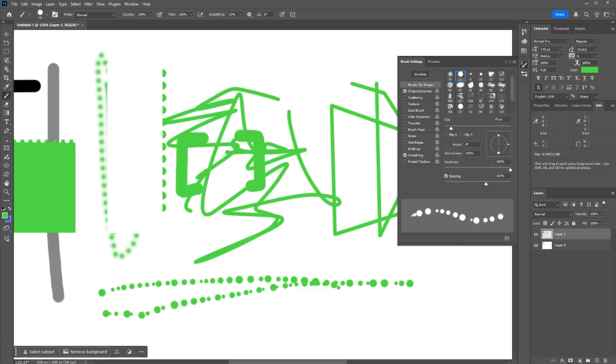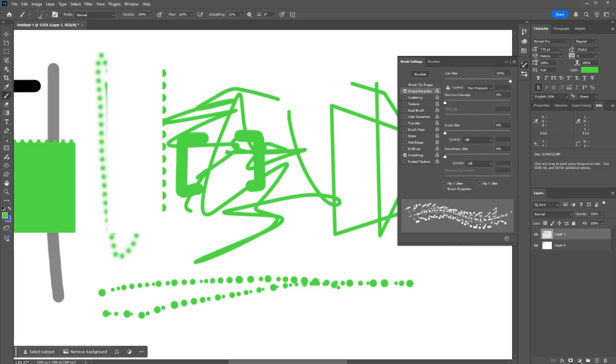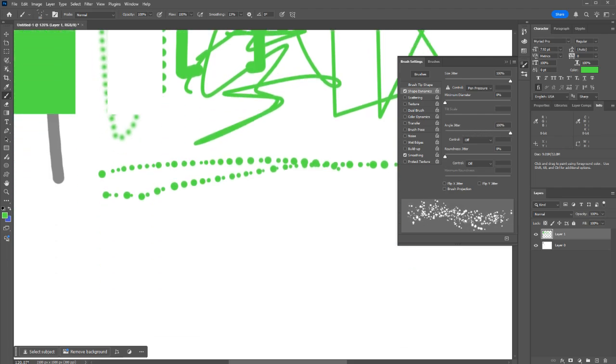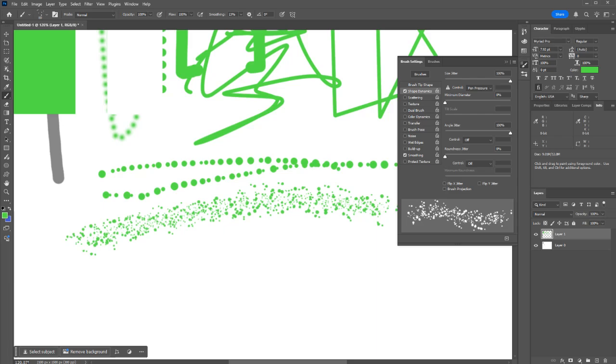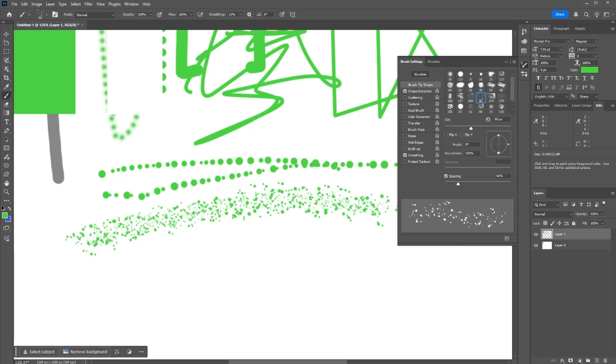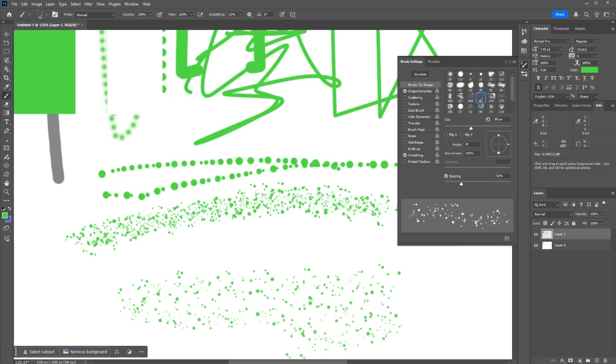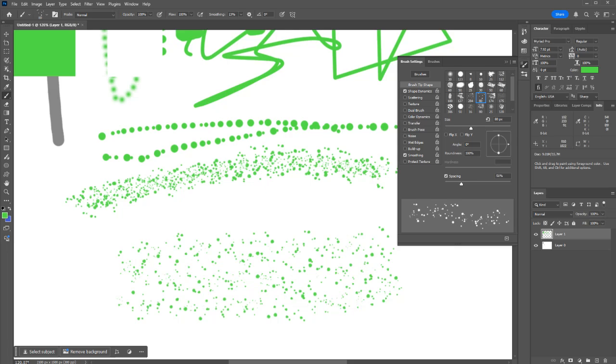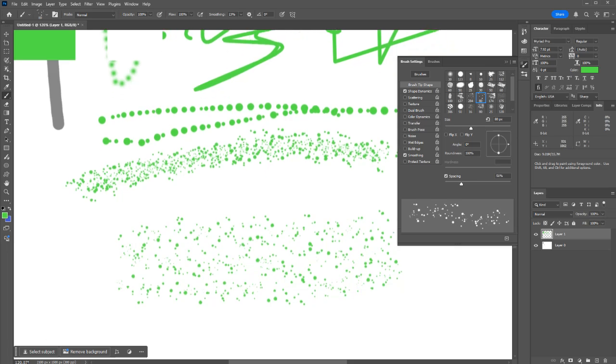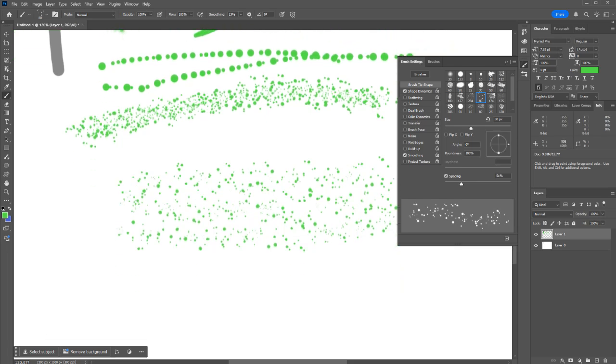So if I was to go back here and choose something like this, we could change it. See how they're all spinning around randomly? So if you go through here like that, you can create a pattern like that. But if you were to increase the spacing here, you could come in here and try and generate a pattern, maybe for a flooring, if you want to reuse this as a particular type of spotted material that you can't get a pattern for elsewhere.